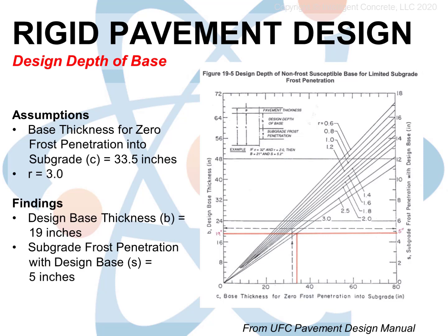If we were to approach our Airfield pavement the same way with the requirement of 34 inches of base and subbase, we've already constructed a sufficient amount of frost-resistant material that frost heave should not be a problem. This approach to design does not mean that we have zero frost penetration beyond the base and subbase layers, only that we will have limited frost penetration. In this case, 5 inches is that amount of penetration, and that amount of frost should not cause significant structural damage.